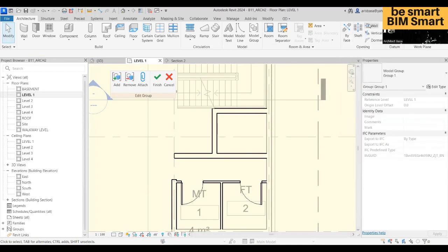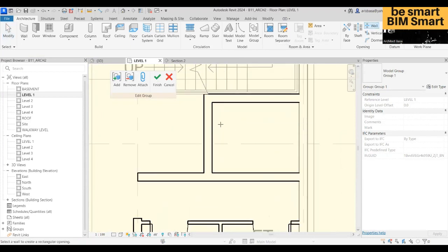So let's click wall opening. How you do it? You just hover your mouse. I'm not clicking anything. Hover your mouse into a wall and click to the end. Say from here, click and hold up to the end.